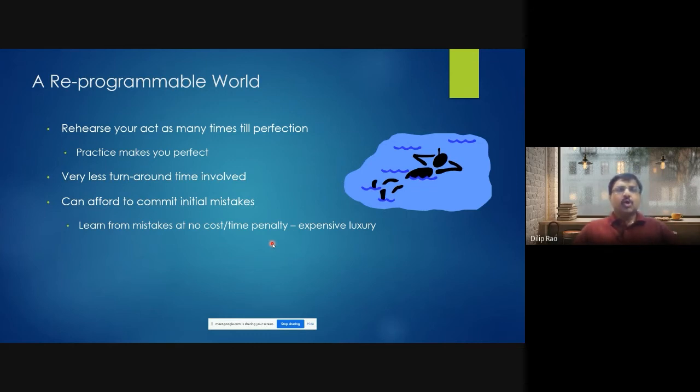All you need to do is verify the functionality, discover the problem, and go back to the design stage to fix it. Most of the time it's a problem in the design, and very rarely it's a problem in the constraints, and then you need to go back to that stage and fix them. You need to come back, build the bitstream, download it, and verify the functionality.